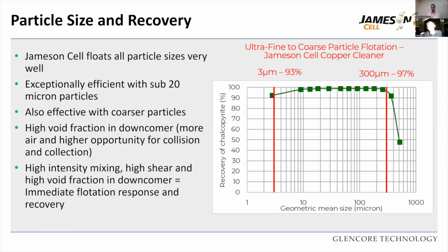So one of the big benefits, as I said, is that with that high intensity mixing zone within the downcomer, particle bubble interaction is virtually instantaneous. So when it comes to residence time in comparison, the interaction of bubbles and particles is virtually instantaneous. So residence time doesn't become an issue for Jameson cells like it does where you're relying more on probability of bubble particle interactions like your mechanical cells and other flotation devices like that.